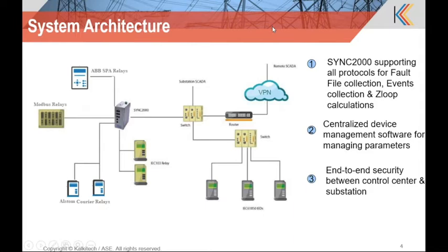We have a power system enterprise suite available at the center, using which it can launch the respective IEDs or relay tools and do the configuration from the center to all the IEDs. So we have a server client installation. At the center there is a server, and there can be power system enterprise suite clients installed at the multiple substation level, and sitting at the client, anybody can configure any of the relays with the credentials, and his roles are mapped to the functionality he is permitted to do.